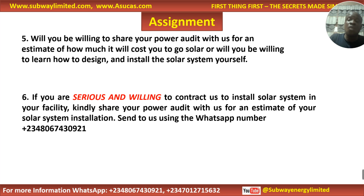An estimate gives you a rough value that will assist you to budget. So if you send me 5 kVA, I look at the load you are using, I look at the hours you will be using the load. I know that, okay, this 5 kilowatt storage battery will not be enough with 5 kVA. If you send me load, I know, okay, 10 kilowatt storage, but I'm not sending you a quotation, I'm only sending you an estimate so that you can adjust your budget.